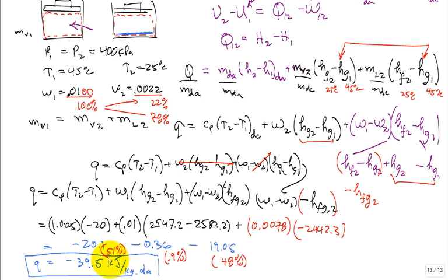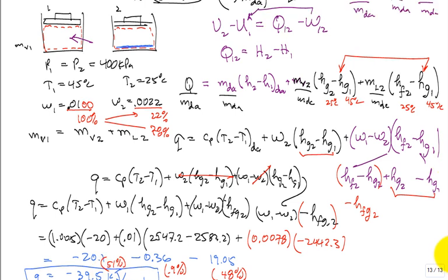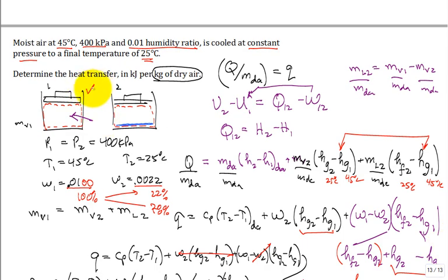But you can see now, if I put that hot air with that humidity ratio in a tank, I just let it cool, I'm going to get a liquid in the bottom. Quite a bit of that vapor will become liquid. In this calculation, 78% was liquid.